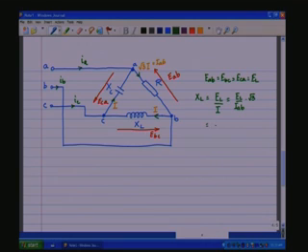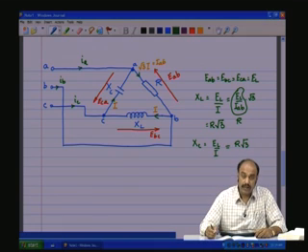Now this is nothing but R, the resistive component of the load. So, this is R root 3. Likewise, XC, the capacitive reactance, is EL by I, which results in R root 3 value wise in ohms. So, this has a nice important implication. What it means is that,